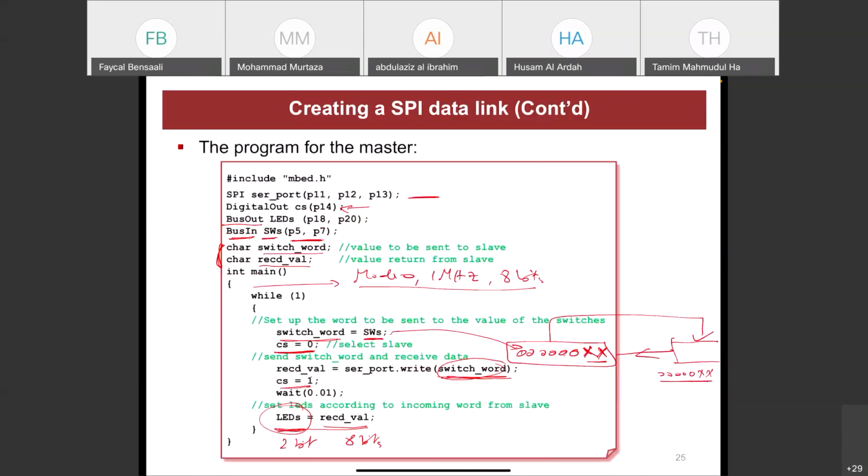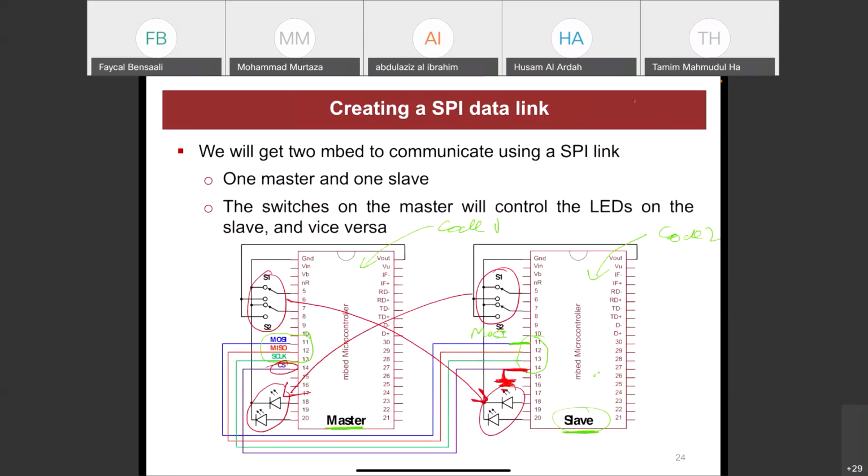This is a very simple example, but usually, in real applications, sometimes you have embedded systems with multiple microcontrollers, when you have to do computationally intensive tasks. So one microcontroller cannot take the whole load, and it needs to be shared by different microcontrollers. And then, of course, one will be the master, so the others will work for it. They will do calculations and then send the result to the master. And the master will use the result and do things that it needs to do. So one is like managing, and the others are working for it, getting the data, calculating the data.